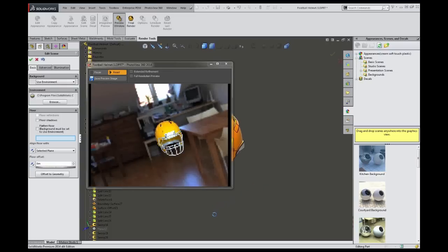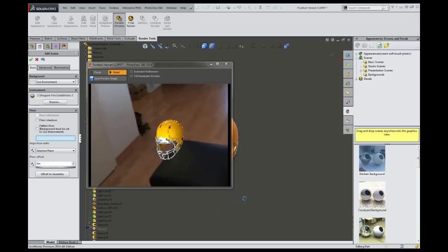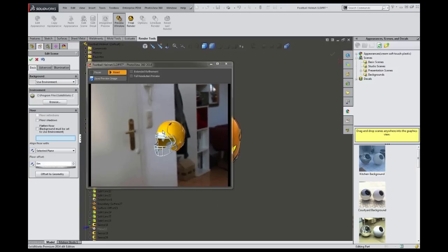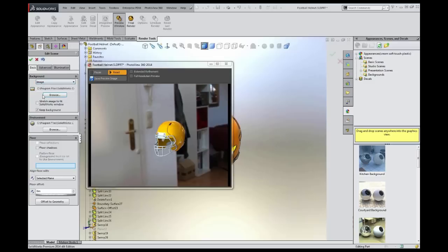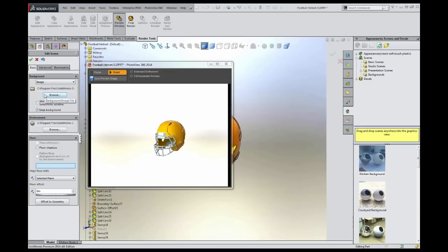little bit blurry of a background anyways. But the main thing is that they're not meant to be backgrounds because you're never going to orient it just perfectly for the image that you have. And it's always going to look like it doesn't match the perspective because, again, this is a spherical image. So I usually never use environment because the main purpose of the environment is to provide lighting and provide reflections on your actual helmet. If I wanted to, I could take an image of the Brown Stadium, use that as my environment, and allow the stadium to actually reflect off of the helmet. But still, for the background, I would probably take another image of the stadium and use that as just a 2D flat image background, maybe of the ground and maybe of the stadium in the background as well, and then I could strategically position my object on that.